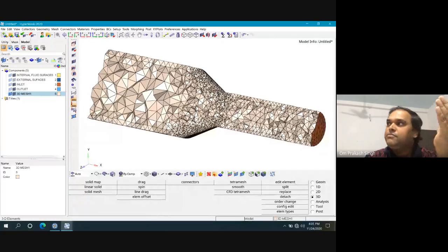In a sense, if you have a 2D mesh, it means one dimension becomes nil. With only a couple of thousand mesh elements, you can generate a really good result, and it will be very fast. Very fast means, depending on the situation, maybe around half an hour or 20 minutes. With one simulation, you can generate a lot of data sets for research and publications.